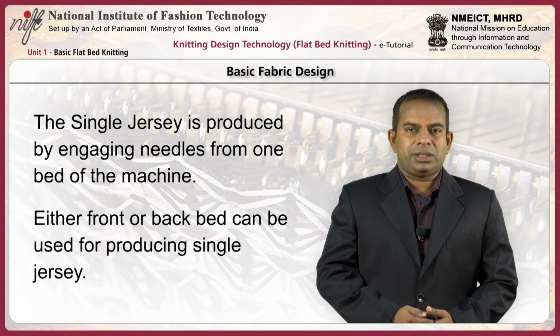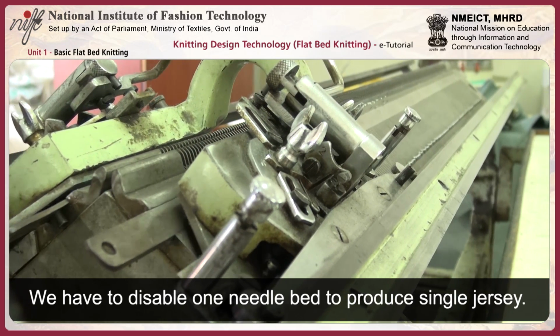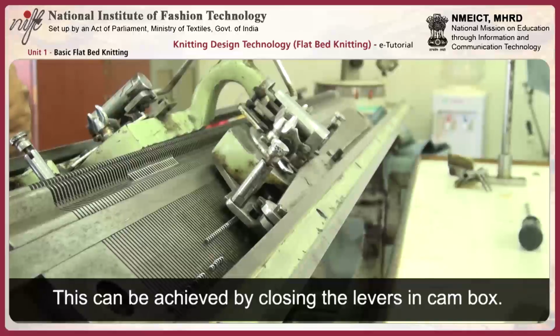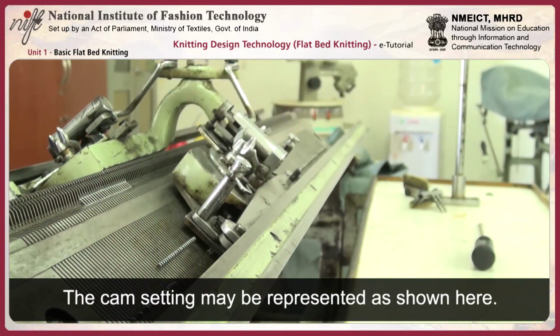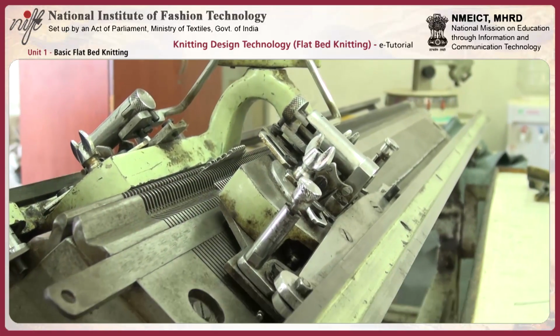The single jersey is produced by engaging needles from one bed of the machine. Either front or back bed can be used for producing single jersey. The loop diagram for a single jersey can be drawn as shown here. We have to disable one needle bed to produce single jersey. This can be achieved by closing the levers in the cam box. The cam setting may be represented as shown here.